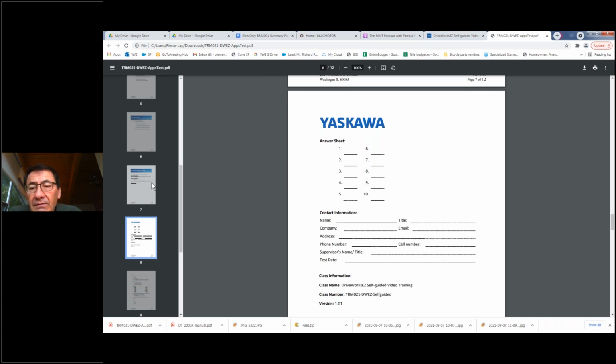One of the challenges I ran into, and it took a little bit to solve, was the velocity ratio that I'm referring to in this constant displacement decel program, where everything in DriveWorks EZ is in percentages. And I needed to calculate a ratio, a number, and then use that to modify the decel rate. And I found that to be, shall we say, less than intuitive.